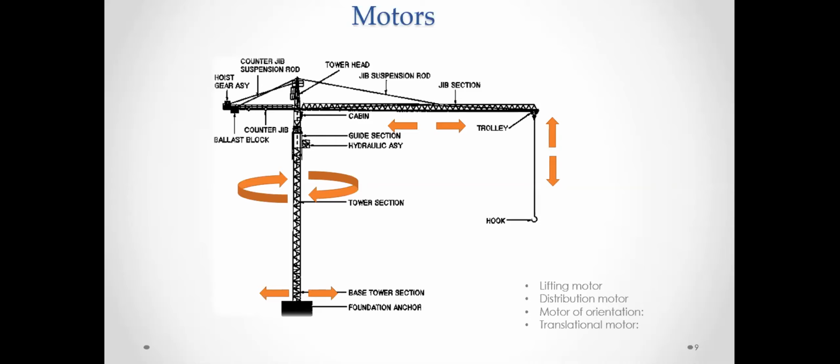And then we have the swing mechanism that we talked about, that will drag the bridge arm to conduct a revolving movement with the shaft at the center, and it is for preventing line deflection. It's mainly constituted of a double motor, and the deceleration mechanism has a braking device.